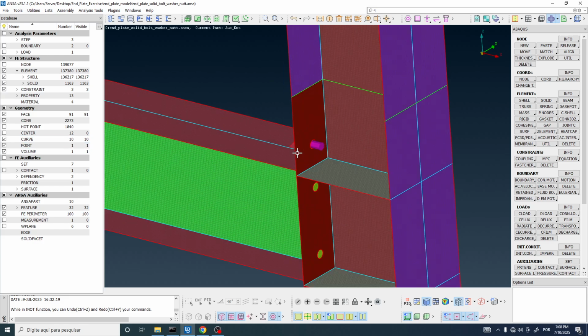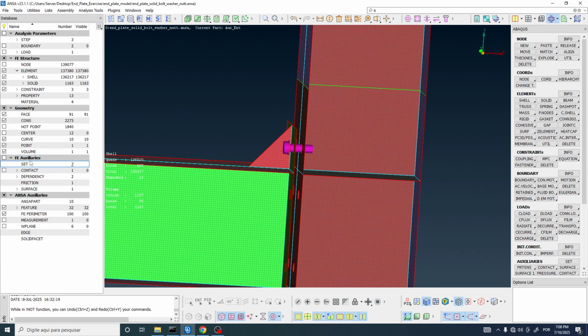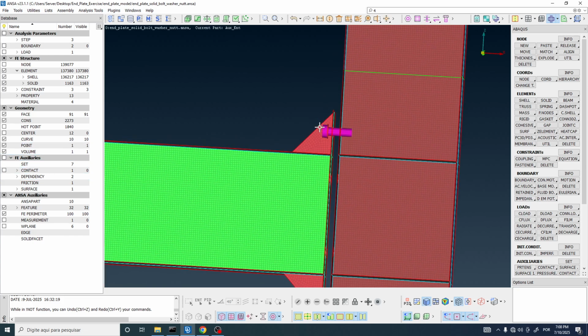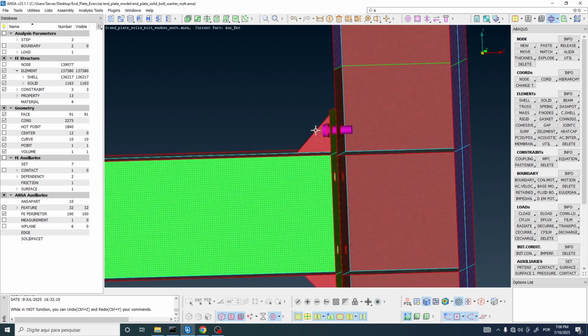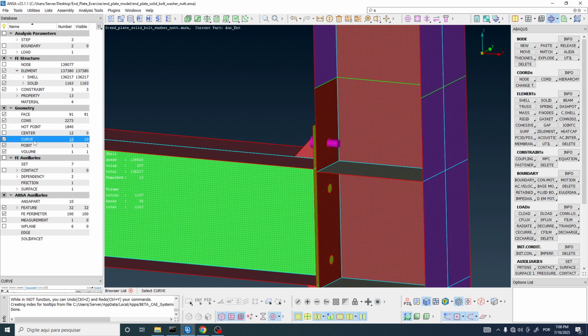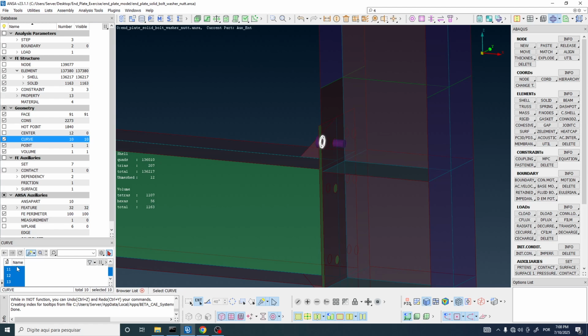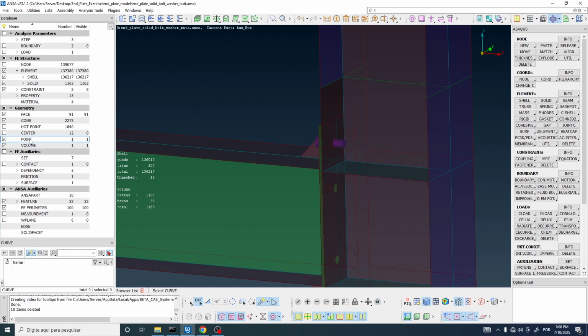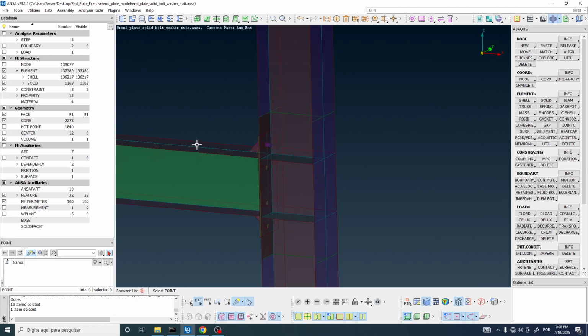And let's do one thing here. Let's delete all points and curves, because now we are going to create some new ones, and I don't want to get confused by the ones that exist already in the module. So double click on curve, Control A on this list, right click and delete. Okay. Now double click on point, right click and delete, and okay.